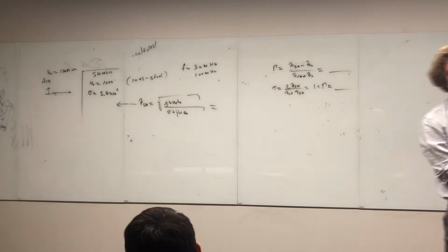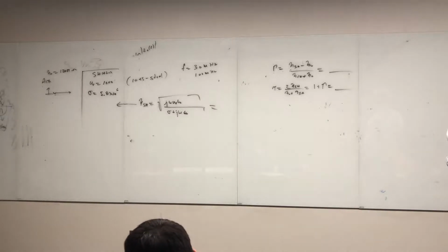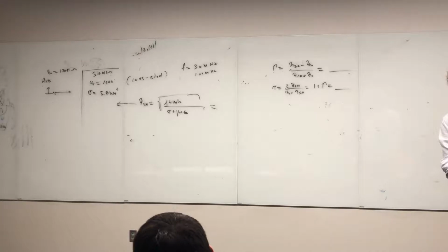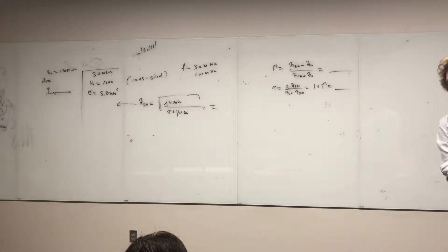And we can get it in dB too, right? We can take 20 times the log of the reflection coefficient, which is called the return loss. And then 20 times the log of the transmission coefficient is the insertion loss. But for now, you tell me what that is. Do they want the reflected losses or the reflection coefficient? Okay, what is it?